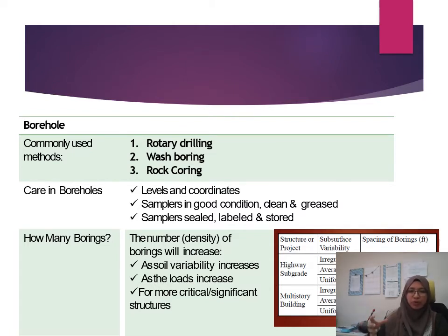So you have to provide container, okay, and then you have to label each of the container. What is the type of borehole, its coordinate, okay, the depth, and so on. And then it must be properly stored. Right, so this is some of the common questions.